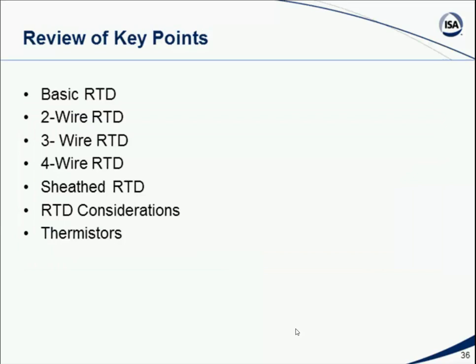All right, so we've talked about RTDs, resistive temperature devices, as a general category of sensor device whose resistance varies by temperature. We said that the most commonly used RTD-type device is the platinum 100-ohm RTD, which can come in a 2, 3, or 4-wire configuration. Again, 2-wire means you keep the lead wires very short because they do have resistance and you have to correct for it. If you can't do that, then you go to a 3-wire RTD where there's an extra lead that allows you to measure the resistance of that lead. Or if you're in a laboratory environment, you might even use a 4-wire RTD.